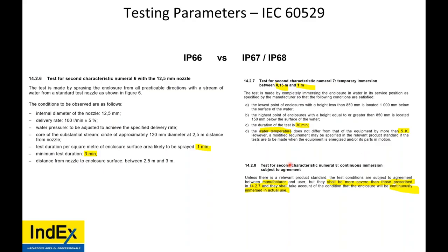Now, 68 is defined by the manufacturer, but shall be more severe than 67. And you shall take into account the conditions of the enclosure for continuous immersion in actual use. So 66, jets of water, 3 minutes.